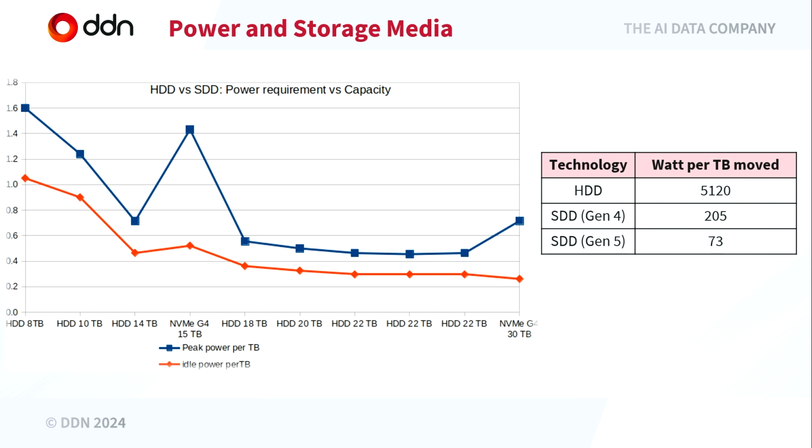And there are 2 bumps. The blue one here on the right is related to NVMe. So basically, the NVMe is more power greedy than the hard drive. So if I have a strong power constraint, maybe NVMe is not the right solution, and I should go for hard drive. Now, if the system is idle, what you can see is that my NVMe, which is very bad when there is a lot of activity, is not too bad when it's cold, if I can say so. So this plot somehow hints that we should go for something based on hard drive for SKA.